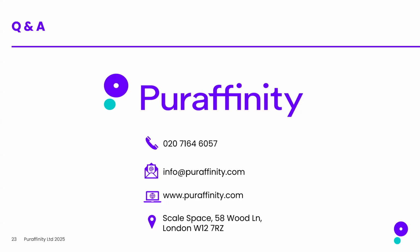Can I use PureTech G400 as a drop-in solution for my GAC vessel? No, and again, it gets back to engineering. It's not necessarily a performance thing. If you look at a carbon vessel, typically the bed depth of carbon in a 10-foot, 12-foot vessel is maybe 6 to 8 feet. Our vessel here, because of the flow rates, the linear velocities and contact times, you'd end up with a very, very thin layer of our material if you put it in there. And again, flow distribution could be an issue.